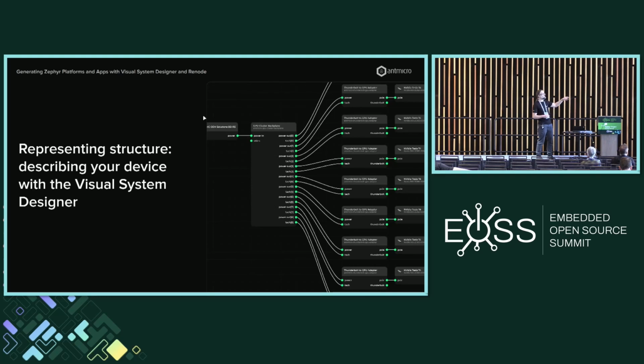It's not a schematic, right? It is a block diagram, so it operates on the level of I/O, like SPI, like I2C, like PCI Express, or connectors that you connect physically. So this actually presents this GPU cluster. There's 8 different GPU units and the main board. It's a pretty nice structure because, of course, it's very logical. You just want to run 8 GPUs together and coordinate between them. So you can describe your device this way, and that gives you a lot of interesting capabilities.